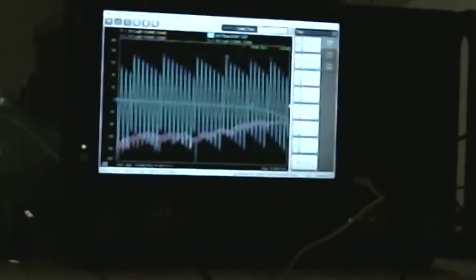And if you take a look at the network analyzer, this is a very key spec for the cables that you would want to connect here. What that does is that as you bend the cables and come back to a certain position, it does not vary. Very good cables will change maybe 1 degree over 26.5 gigahertz as you bend them really, really tightly. All I did here was just do this, and I can see it.